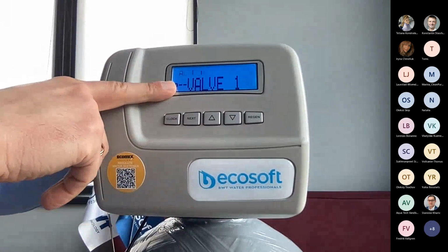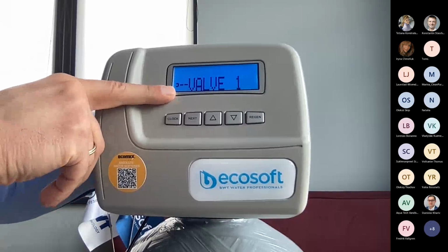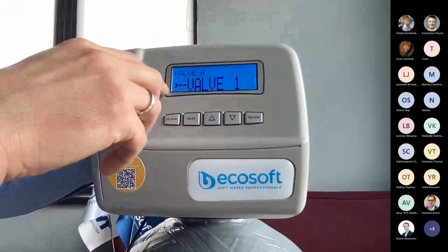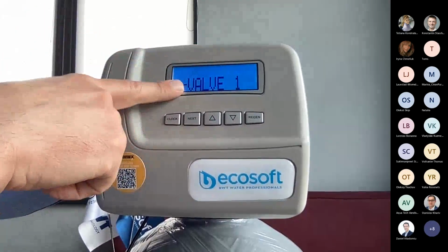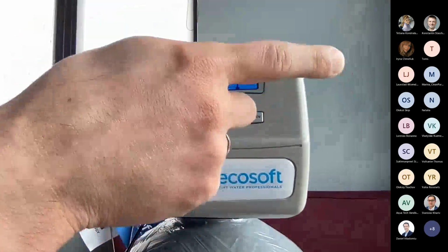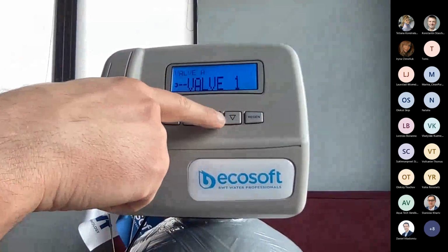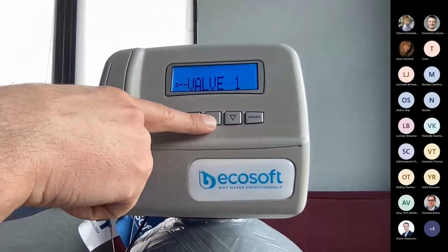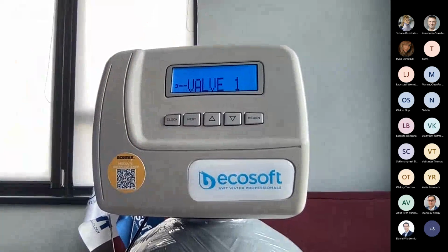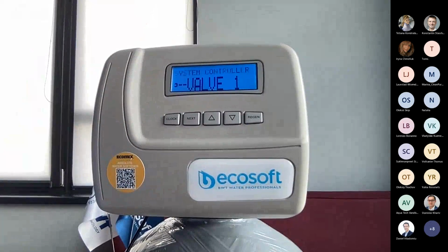If you are setting a twin system or alternating system, and you want 2 valves or 2 systems to work alternately, then the first system will be set as valve A, and the neighboring unit will be set as valve B. Also, you may connect the system to the Clack system controller, and you have an option to build a system that consists of up to 6 units. From 3 to 6 units, you may arrange them to work in parallel.